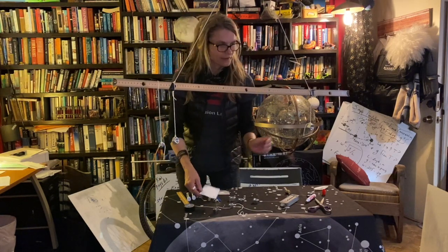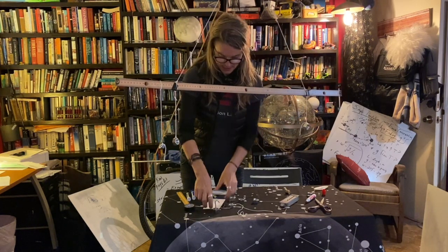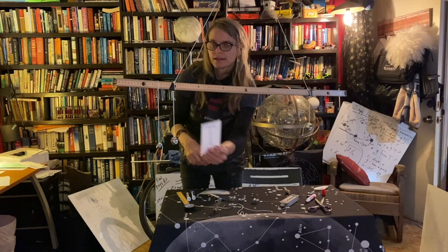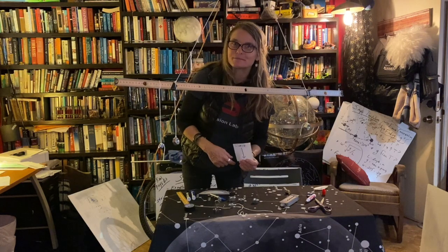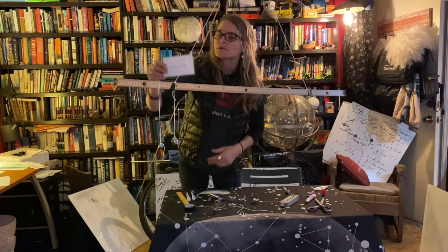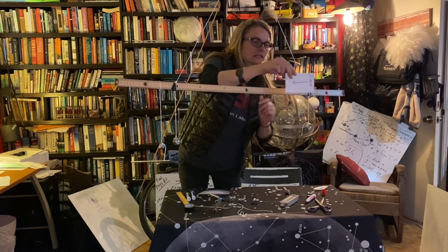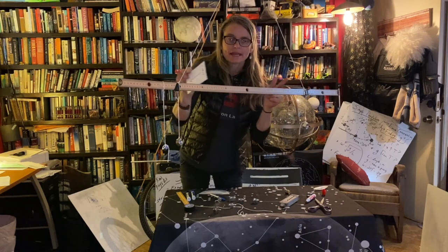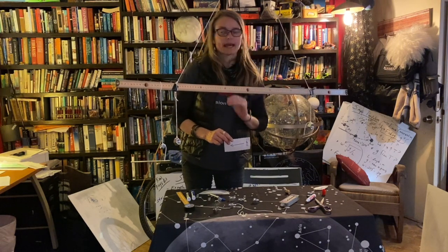So we have several forces. If we look at our translational forces, we have upward forces, this upward force, this downward force, this downward force, this downward force, and this downward force, all sum to 0. So the sum of our translational y force is 0. But we also have the x component of our force this way, and the x component from tension acting this way, and these two cancel each other out. So that sums to 0. So we have translational static equilibrium.